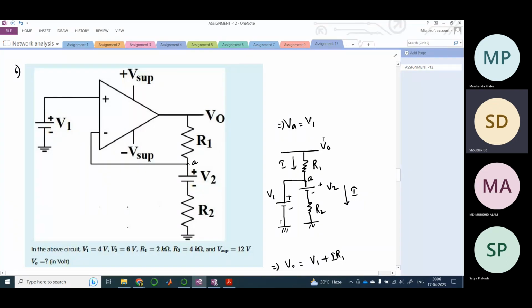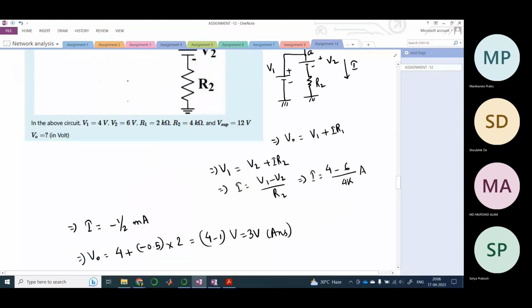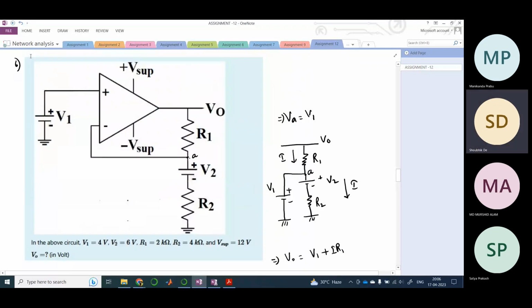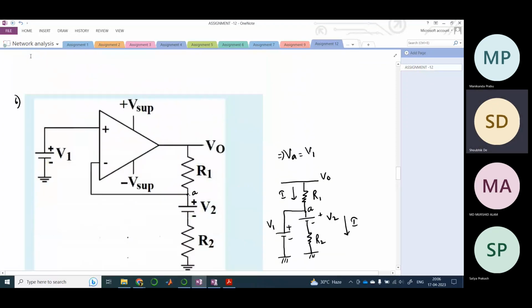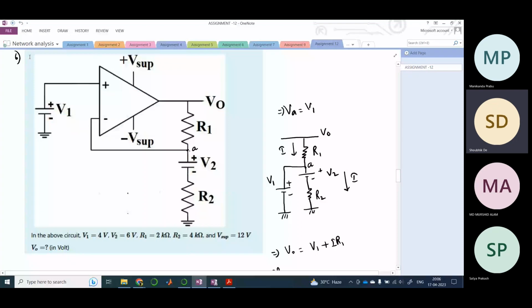For example, if there was a resistance here and a feedback path something like this, then a current would have flowed through this path. But this is directly connected, so let me just remove this. This is a direct path connected to the non-inverting terminal, and we can totally remove this part out of the circuit.